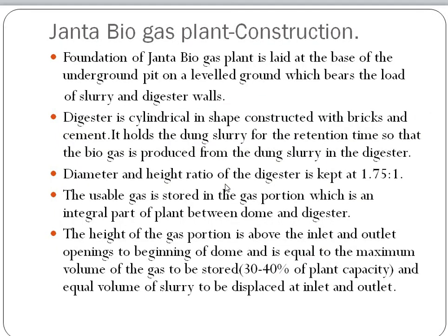We will understand briefly about the Janata biogas plant. It is laid at the base of an underground pit on level ground, which bears the load of slurry and digester walls. The ground should be firm enough to bear this load. The digester is cylindrical in shape, constructed with bricks and cement.